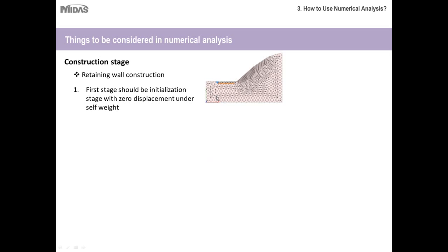So you'll just model the existing soil strata in whatever state it is, and set the displacement after this stage as 0. So whatever has happened prior to our construction is our initial condition now, and whatever happens thereafter is something we'll monitor.